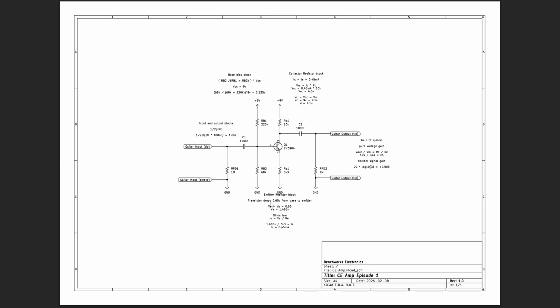So this, generally transistors lose about half a volt from pin 2 to pin 1. So when you're measuring this, you'll see 2.1 on pin 2, and you'll see around 1.4, 1.5 volts on pin 1.